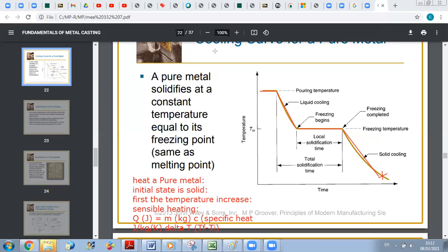And in case you are moving in the opposite direction, before, at the initial state, your metal is solid. You need to heat it before pouring because you cannot pour your metal in the solid state. So first you should convert it to liquid to be poured in your cavity. Then when it takes the cavity shape, you cool it until total solidification. This is why these processes are called solidification processes, because they rely on first melting the solid in order to pour it in the cavity, and once it takes the shape of the cavity, we keep it to cool in order to get the final product.